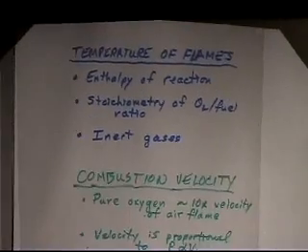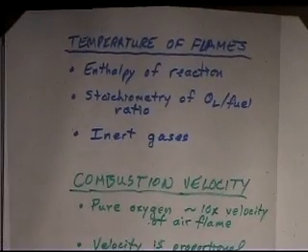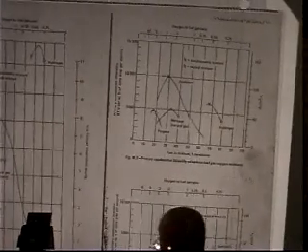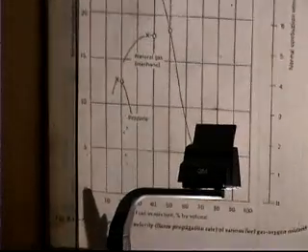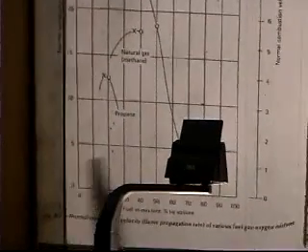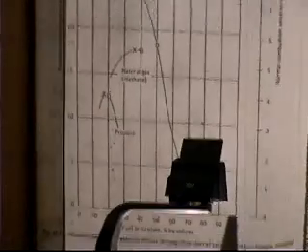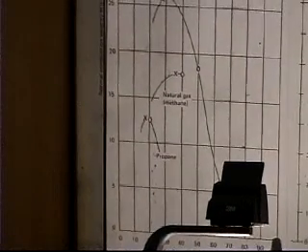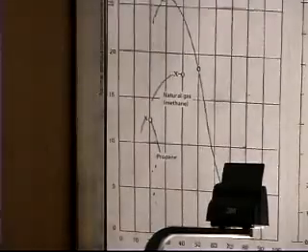If I look, this comes out of the welding handbook, at the oxygen to fuel gas ratio as a function of the fuel in the mixture. So we're looking at 100% fuel, 0% fuel. Well, obviously there's a 0 point down here, because if it's all oxygen and no fuel, then you don't get much heat, much temperature rise. And if you look over here, at 100%, you don't have any oxygen, so the thing's not going to burn. So there's got to be some peak in the middle.